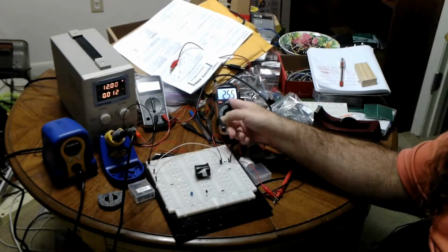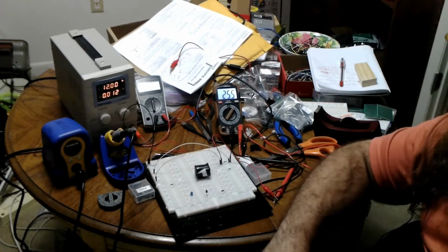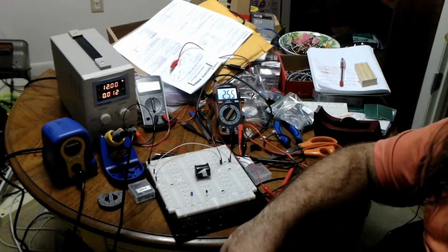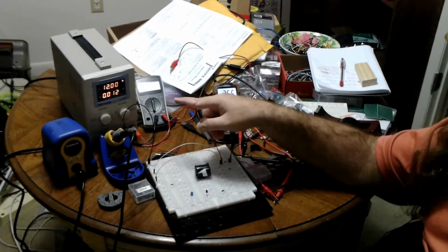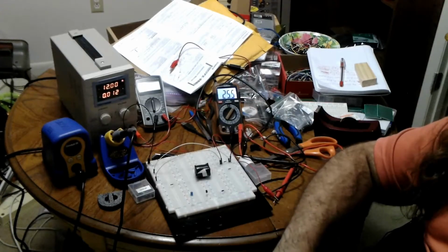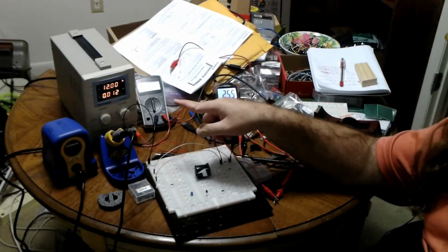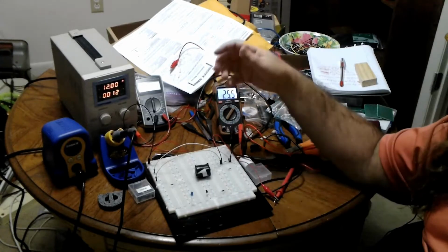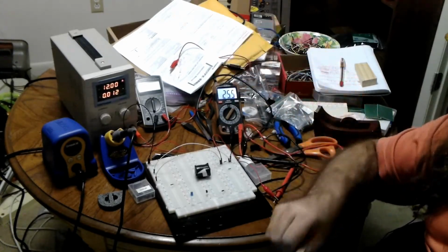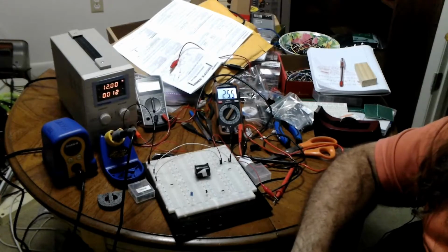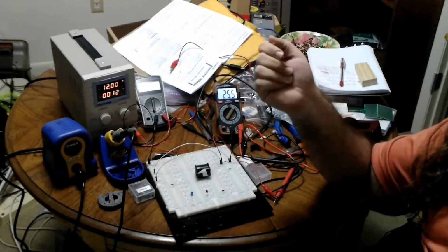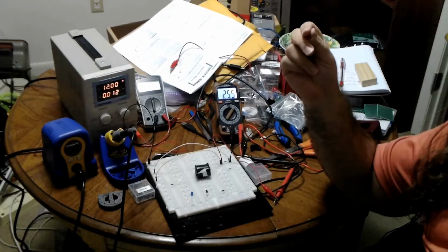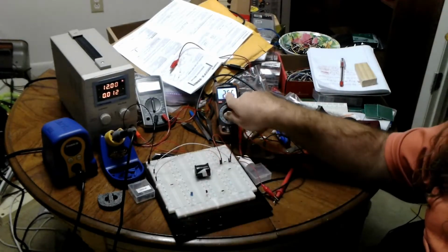25.5, 25.6. Is that roughly double 12? Double 12 is 24. But it's not, you say. Not so fast. What does a diode have? It has a voltage drop, doesn't it? Well, 25.5 minus 24 that we expect is about 1.5. What is half of that? If we're doubling the 12, what's half of that? Well, half of 1.5 is roughly 0.75. Well, it is 0.75. I'm saying it's roughly measuring that. What does 0.75 sound like to you? Well, a lot of diodes have a forward voltage drop, just regular diodes, around 0.6 to 0.7 volts. Isn't that interesting?